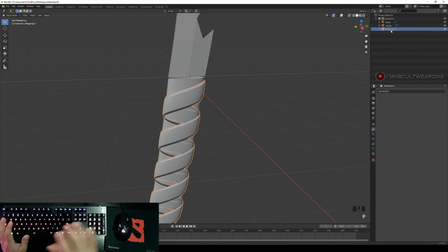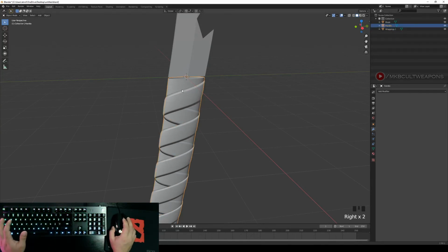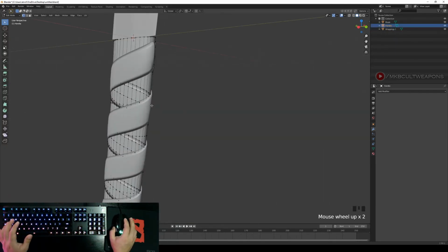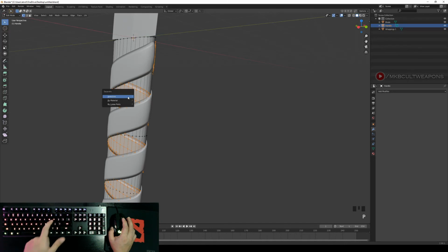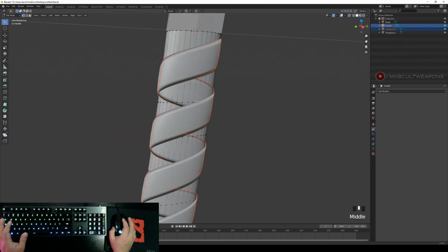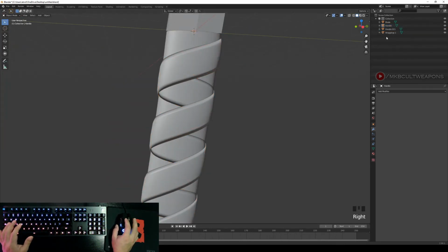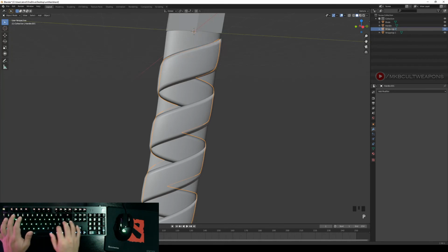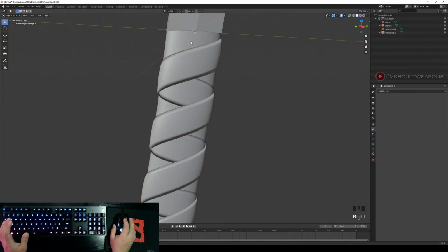1, and we're going to do the same with the other wrappings, the wrappings inside. Just select a single vertex inside, press L, press P, press selection to unlink that wrappings there. So let's just quickly rename this one, wrappings 2, and this is the handle.